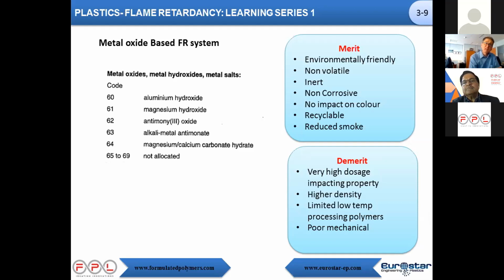So water has different actions. It dilutes the gases. It cools down the polymer. And from my side, it's a very, very nice material because when you are burning such a material, you are releasing only water vapor and CO2. So it's a more environmentally friendly material. So we are working on it a lot. People are working on it a lot. It's very good, for example, for limited oxygen index. For example, people in trains or in tunnels, with more stringent regulation, can use it, but there are some drawbacks still.